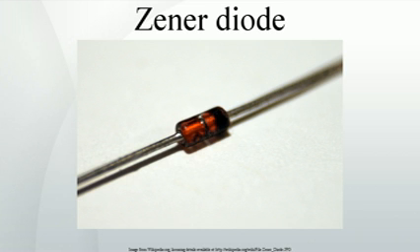Uses. Zener diodes are widely used as voltage references and as shunt regulators to regulate the voltage across small circuits. When connected in parallel with a variable voltage source so that it is reverse biased, a Zener diode conducts when the voltage reaches the diode's reverse breakdown voltage. From that point on, the relatively low impedance of the diode keeps the voltage across the diode at that value.